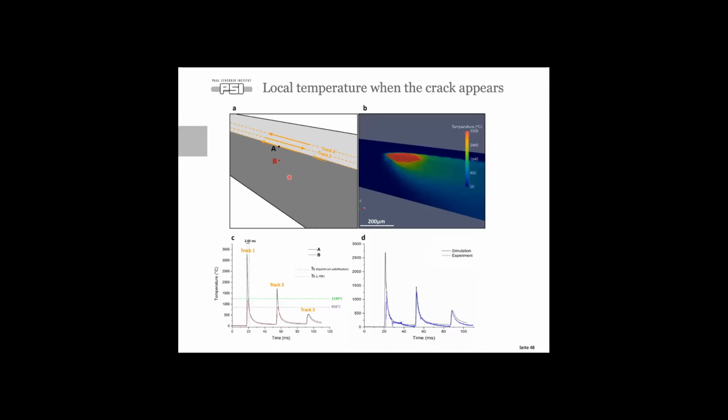This means that we can trust these temperature curves, and we have quite a good proof that this liquefaction cracking is occurring. So based on all these results, we see the two mechanisms. We see solidification cracking, where we have the solid-rich liquid entrapment between the solid phases, and then the tensile stresses create these interfaces. But then also liquefaction cracking: because of the microsegregation, we create local melting at these boundaries, and together with the tensile stresses, we create this cracking in the material.